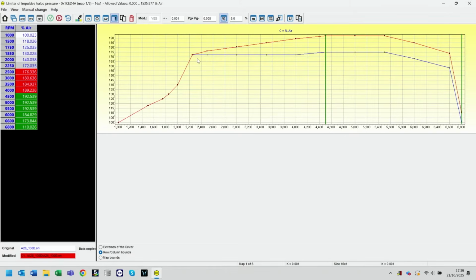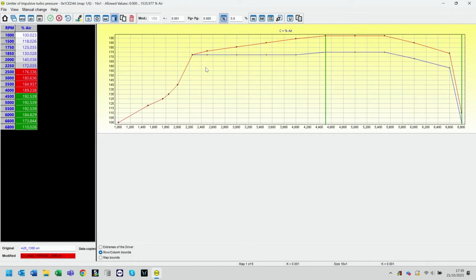So with our Katana Fire package on our Golf R, with all the bells and whistles, the exhaust system, intercooler, induction kit, and so on and so forth with the tuning, we actually reduce the torque load down by as much as 70 Newton meters on some of the maps to give a smooth build-up. So you don't get a huge surge. You don't want it to do everything low down and then not be able to achieve it at the top end. We want to be smooth and progressive and kinder on the components, meaning we have a bigger horsepower output towards the top end. It's more usable, and as I said, it's easier on the drivetrain.